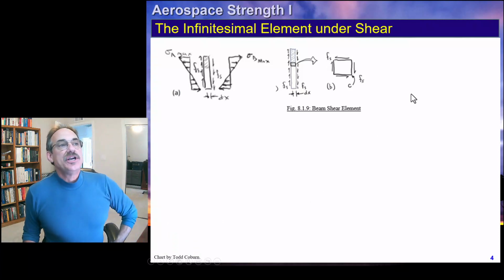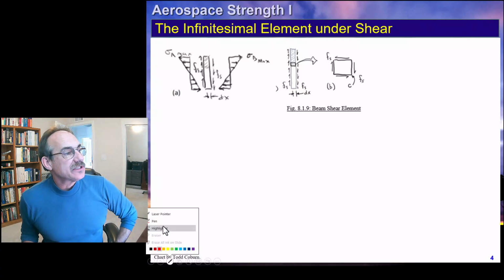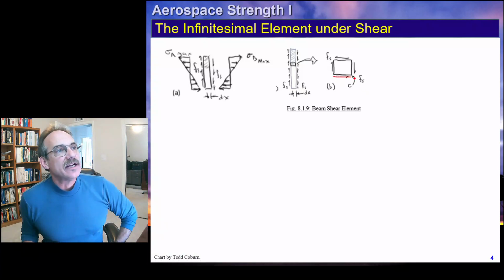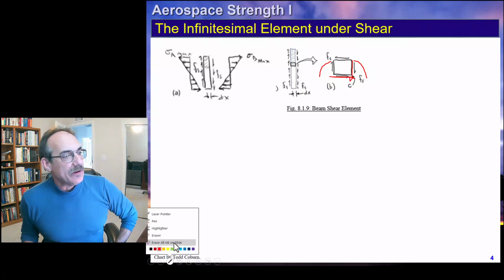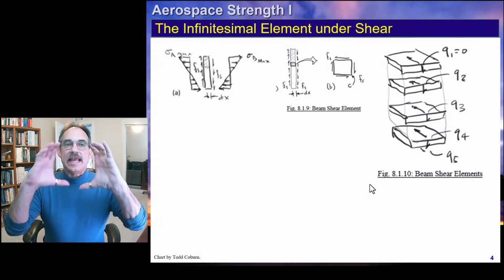And so our shear stress is going from 0 to some value at the bottom that is increasing. Our horizontal slice, you'll notice the stress along here is a constant, but the stress along this face is increasing in a parabolic fashion. This one's increasing in a parabolic fashion, and this is a constant. And that's a function of that first moment of the area and how it influences the shear stress. So we're looking at the end of the thing.